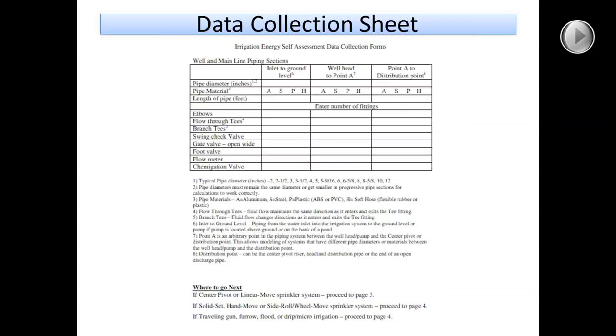We talked about minor losses a little bit yesterday, just briefly. A lot of times they are a minor part of the total dynamic head, and we can usually just use an average estimate of a few feet for those and be really close, instead of calculating the minor loss through each valve, T, branch, meter, or whatever it may be. We'll still be okay just because they are a minor portion of the total dynamic head.